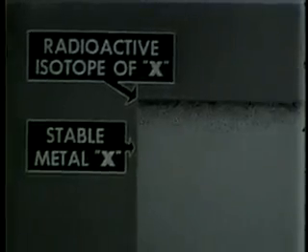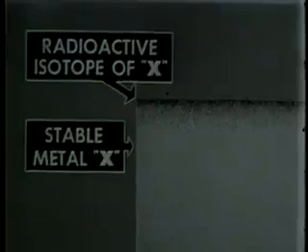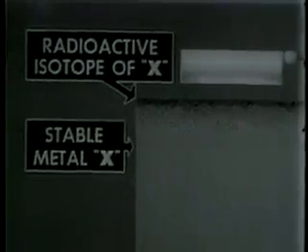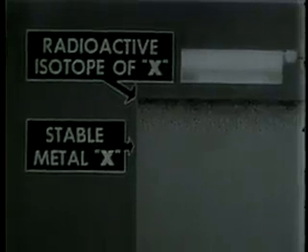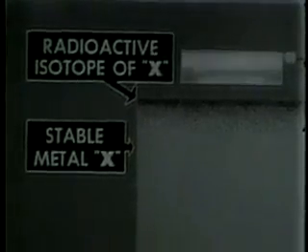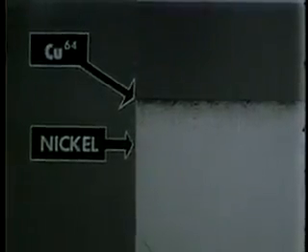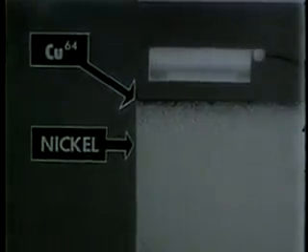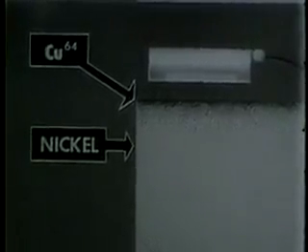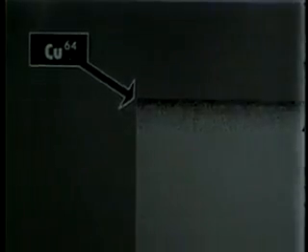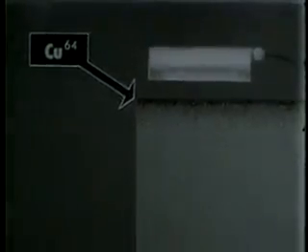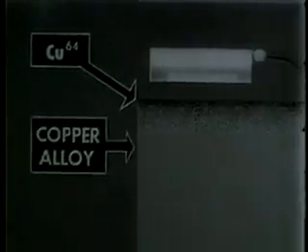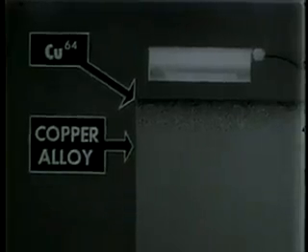The self-diffusion coefficients of other solid metals, impossible to determine by known chemical methods, may be obtained relatively simply by using radioisotope techniques. Diffusion between dissimilar metals may be investigated in a like manner. These experiments are particularly valuable in the study of alloys. For instance, much data can be brought to light through radioisotope work on the diffusion rates of copper into various copper alloys.